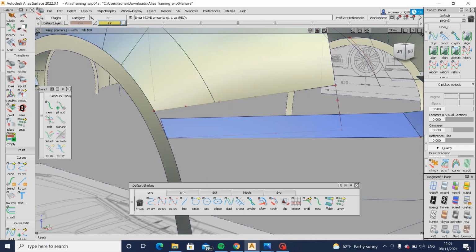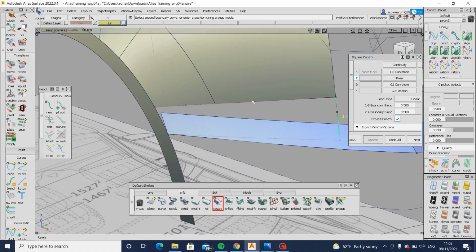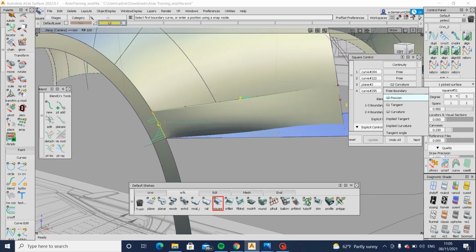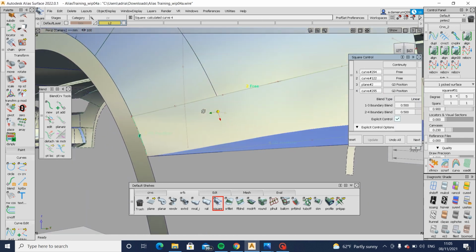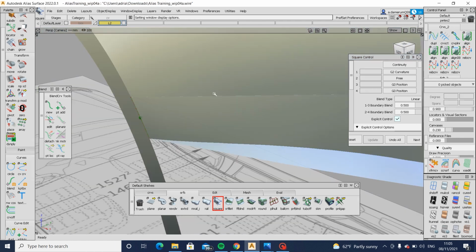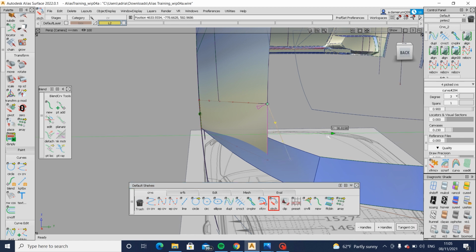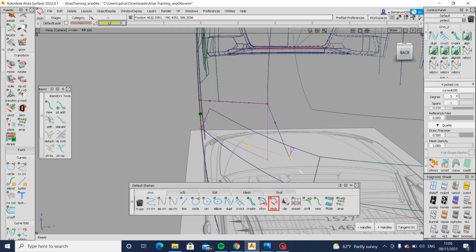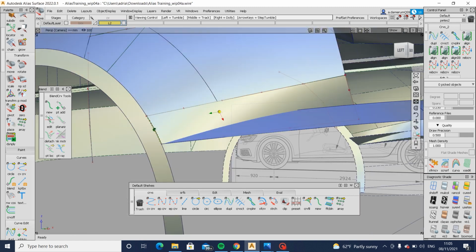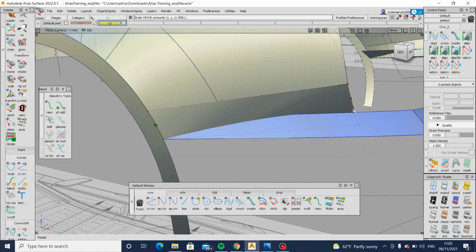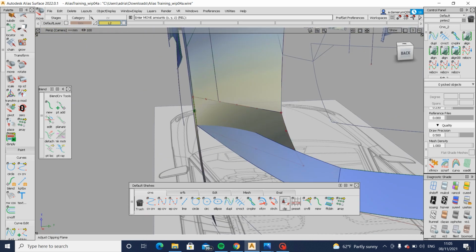Okay, let's build a square in and see what it looks like. 1, 2, 3, 4. Again, make sure everything's positional. Okay, so there's a negative break there, which is not what we want. We want it to be positive, so we just need to pull everything in. So let's stretch this curve in, and then that curve as well. Let's give it some crown though, and see what it looks like now. Better, but now I've gone too far in. But it's doing something similar to what it's supposed to be doing now, which is good.